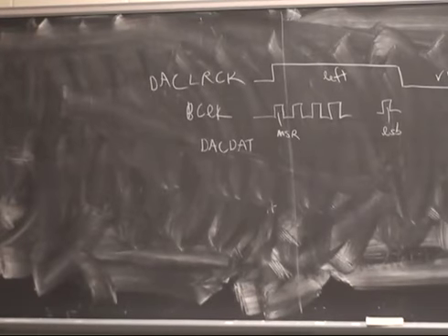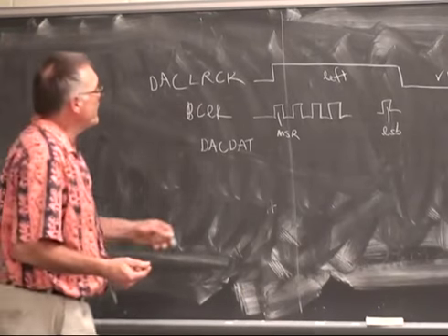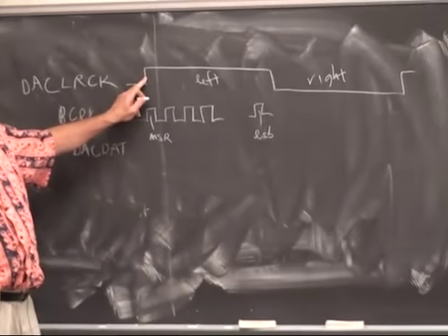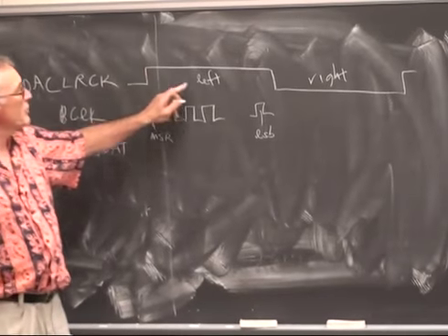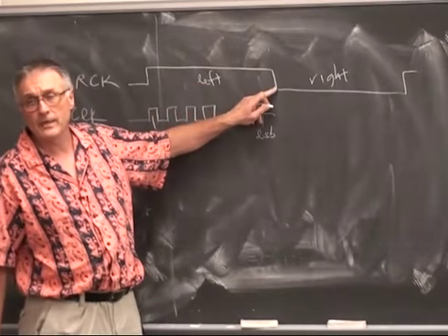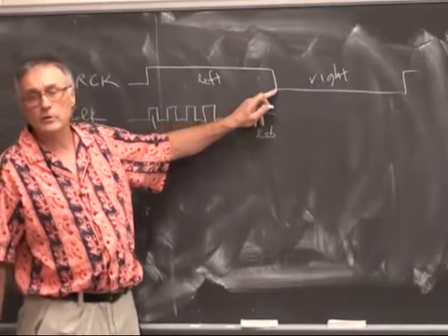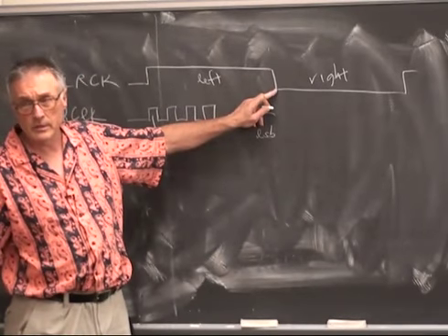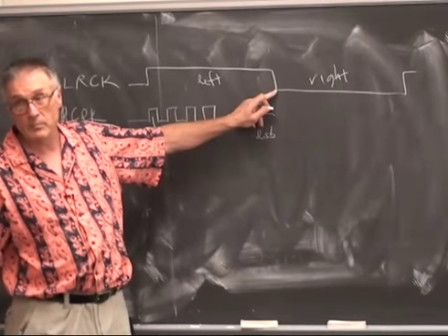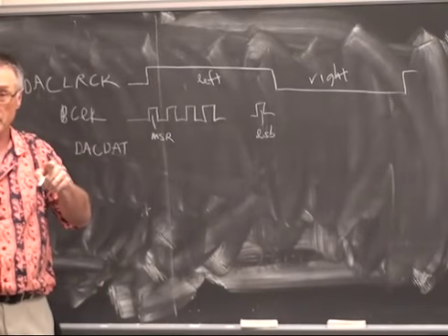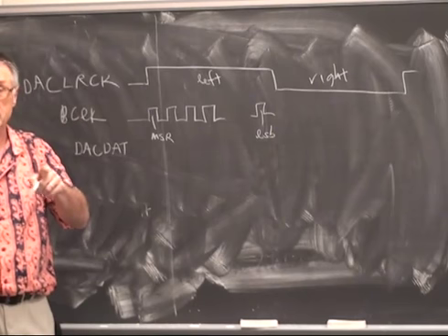I would suggest that at approximately every edge here, you're going to want to have your CPU polling for the edge of this waveform and load a new value into a hardware register, which then gets pipelined into the audio codec on the next cycle.